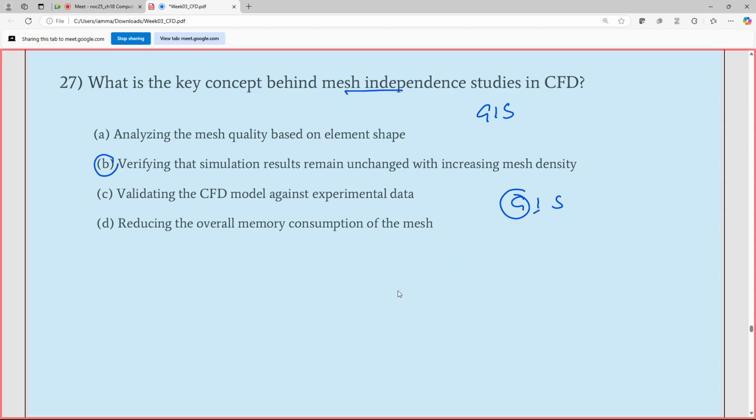Simply put, we have a lot of gradient terms like ∂u/∂x in our equation. This is approximated using the delta x distance in our grid, so the element sizes. Not exactly, but somewhat proportional to this.